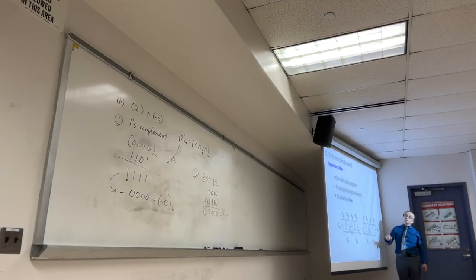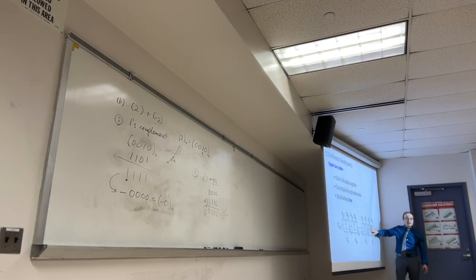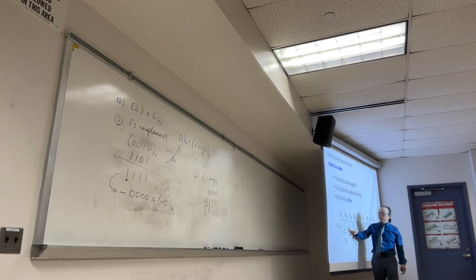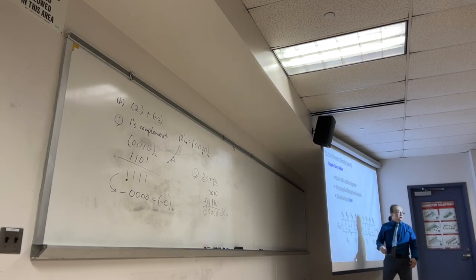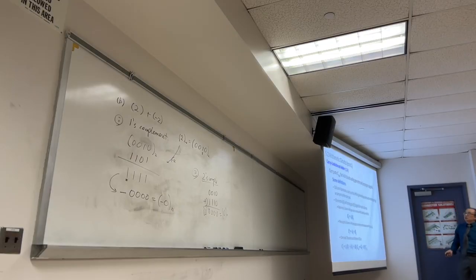So that's why it's a ripple carry. The adder is slow because we have to add from here and then see whether we have a carry here or not, and then add carry or not, add carry or not, add carry or not. So we cannot do it at the same time. So here's another one, carry look ahead.